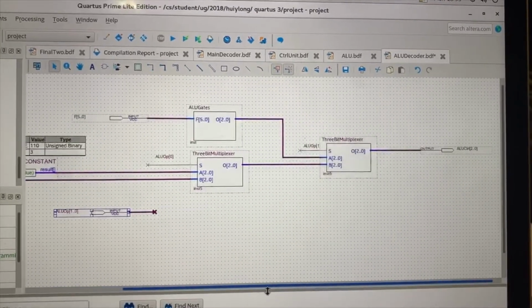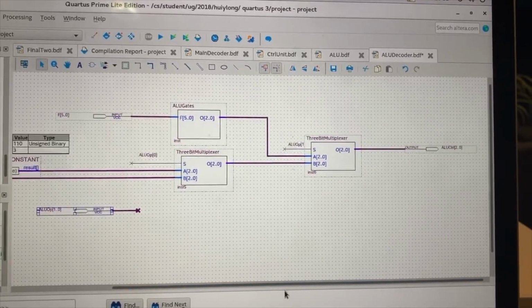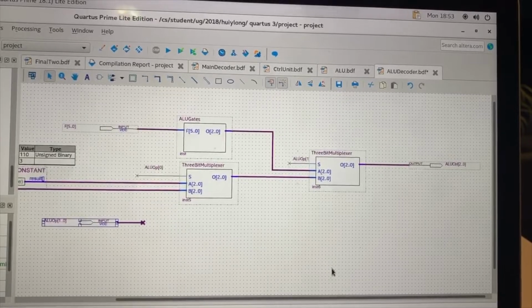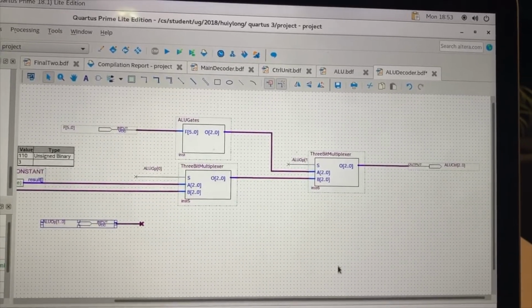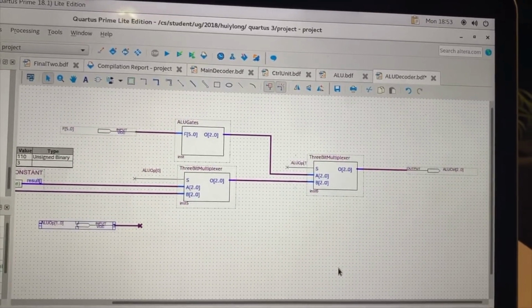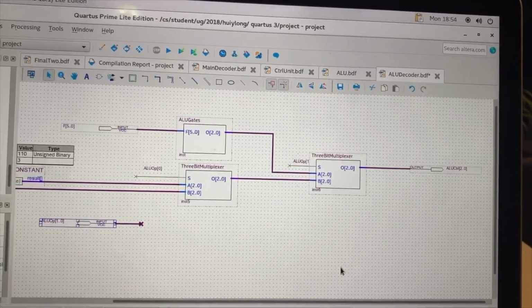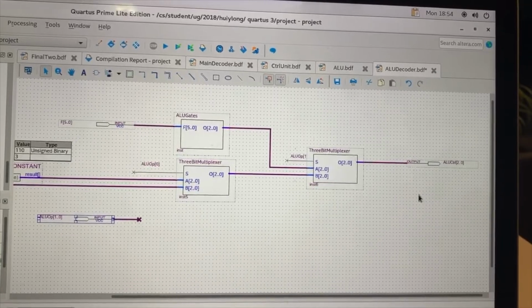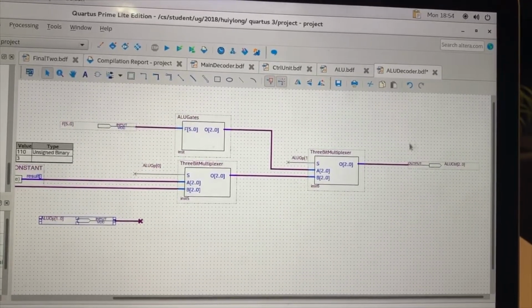In the other case, we use another block consisting of combinational logic gates and the 6-bit function input. Both cases lead to the final output of the ALU control, which is a 3-bit bus line output to the ALU.